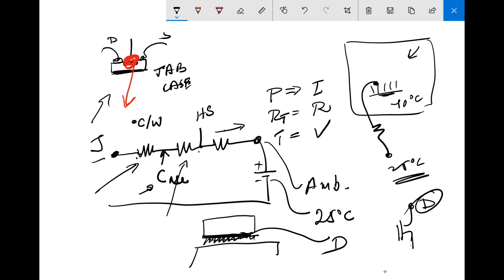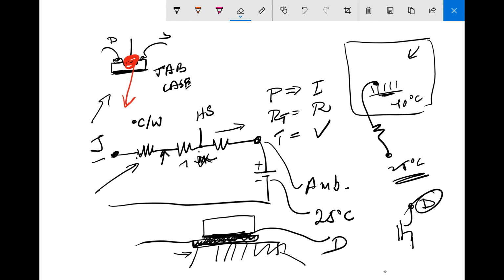And therefore, certainly not for a p-channel transistor, or n-channel transistor. So in this case, you cannot connect it to the heatsink if the heatsink is at ground temperature. And you'd like to keep it at ground temperature. You don't want this heatsink to be all at high voltage. So therefore you put some insulation in here, which adds another resistance. So I'm not talking about this for a minute, because we really don't need it here for our discussion. Let me just erase the stuff that I don't need.